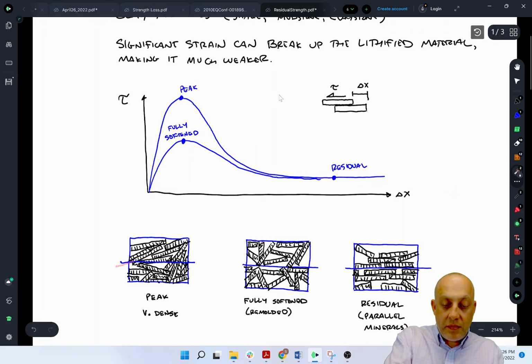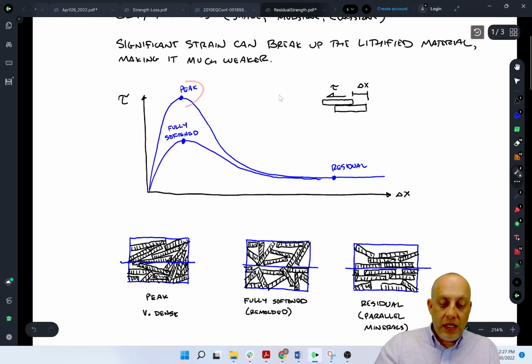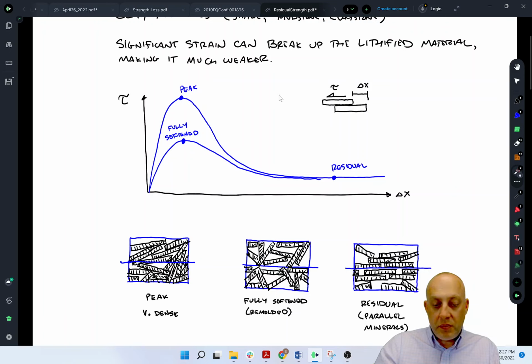So actually it has to come up here and then go down there and break that one and then come up here. And so the true sliding surface is not really a horizontal plane. It's having to go kind of through this tortuous path. And there's maybe a lot of dilation happening. So the soil's particles are growing and loosening as it shears. And that's all happening right at the peak up here.